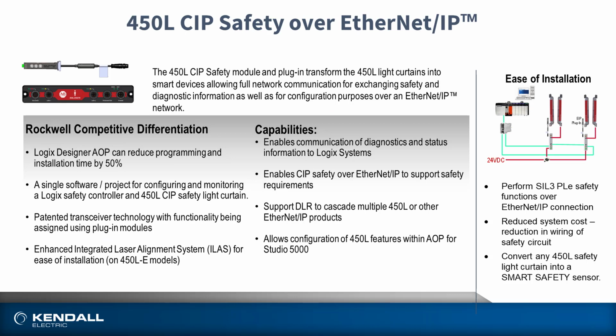My personal favorite today is the brand new 450L CIP safety light curtain accessory package. This includes a new CIP safety module and Ethernet plugin for the 450L. With this, we are finally able to obtain a SIL3 PLe safety category with any 450L light curtain over EtherNet/IP. This promotes ease of use. Now a single software can configure and monitor a Logix safety controller with the 450L light curtain.